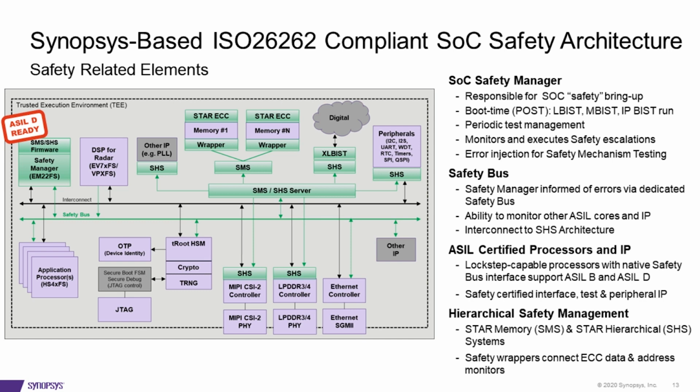Instead of having to wait for whatever delays might be in the system through the interconnect or the peripherals, a dedicated safety bus allows the fastest path to indicate a safety issue to the safety manager. Then the manager, based on the priorities for different areas of the SoC, can make a determination of what needs to be done, whether the part needs to be reset or whatnot.